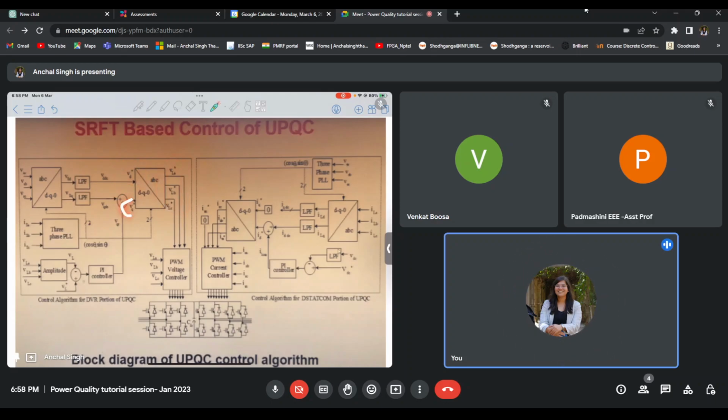Whereas for the Q component, I will add one more component, which is the load voltage at the point of common coupling. Now I know that if my point of common coupling voltage is not equal to the desired voltage, suppose I have a line voltage of 400 volts, then the per phase voltage should be 400 by root 3, that is 230.94 volts.